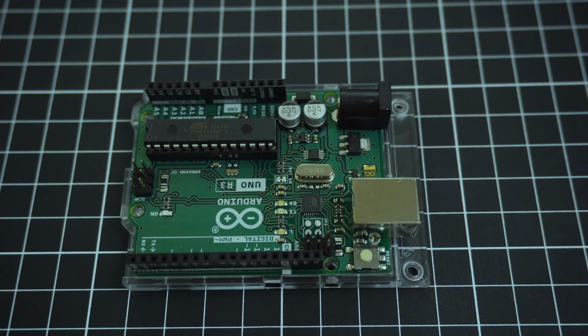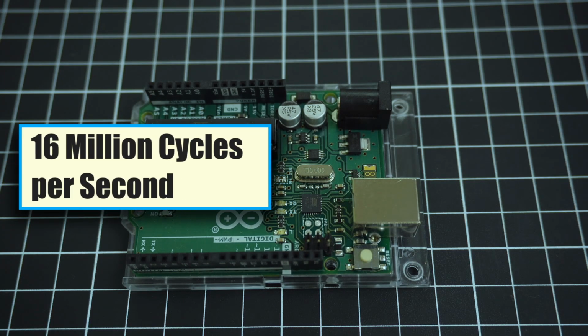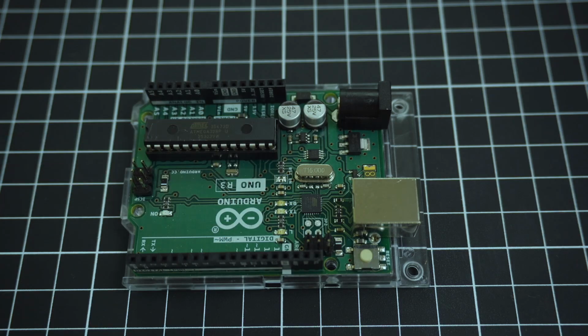The Arduino UNO uses a 16 MHz crystal oscillator to provide a precise and stable clock signal. This means the microcontroller operates at 16 million cycles per second. This clock signal synchronizes all operations of the ATmega 328P microcontroller. In simple terms, the crystal acts as the timing reference that keeps the entire system running in sync.